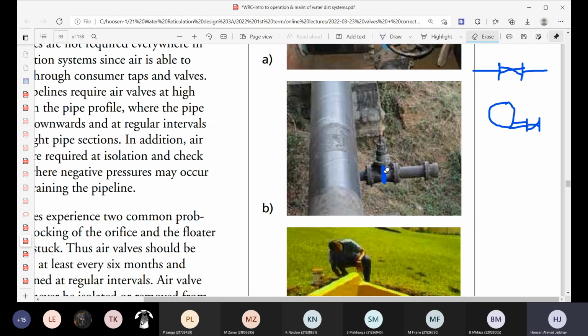When you turn the valve, when you turn the handle, then it slowly screws it upwards. Sometimes the spindle also rises. You also get non-rising spindle valves. The gate would then move to the top position like that, where I've colored it now, and then you can get flow through the valve. Right, so that's why it's referred to as a gate valve. You have like a gate or a sluice in it that you operate with the handle and that goes up and down. But you cannot see it because the mechanism is inside the valve.